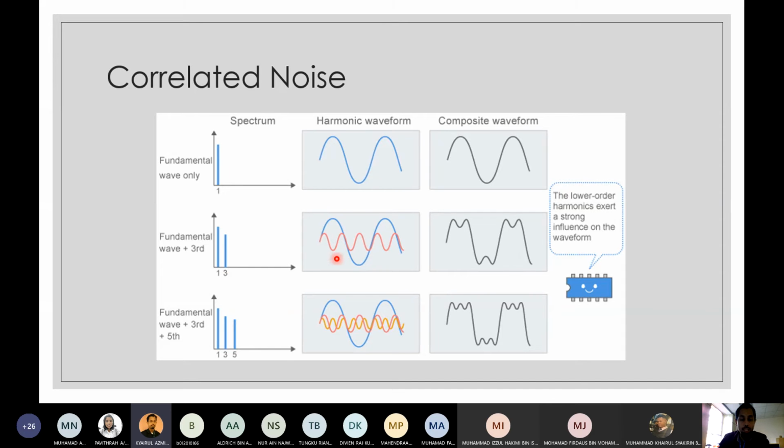So you can see something like the shape of the pink waveform here. So because it's in the same circuit, this wave can superimpose each other. And you get a combination waveform that is no longer nicely shaped like this, but distorted. This is what is causing the overheating or overloading.